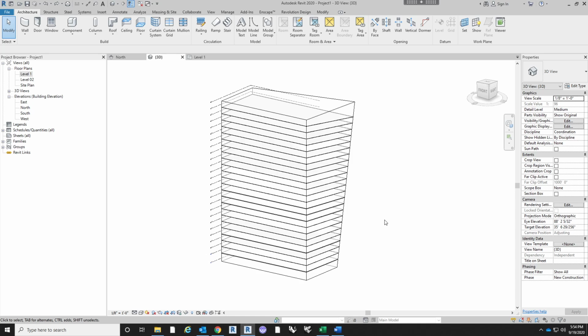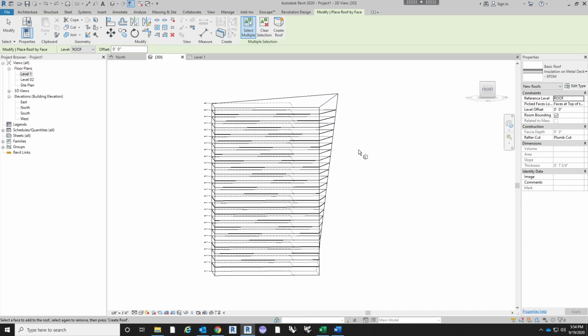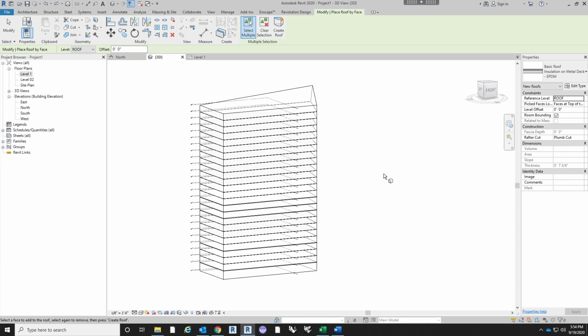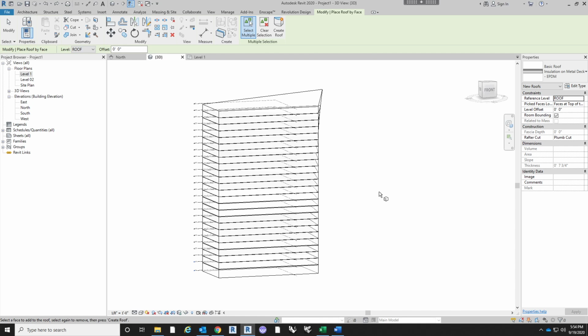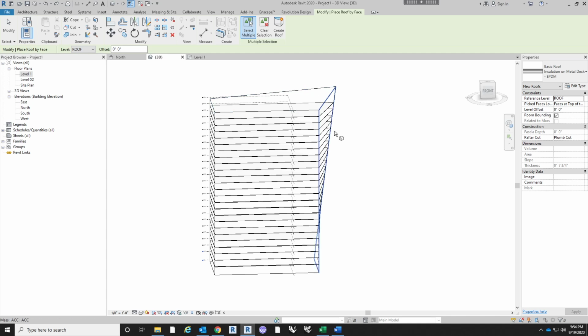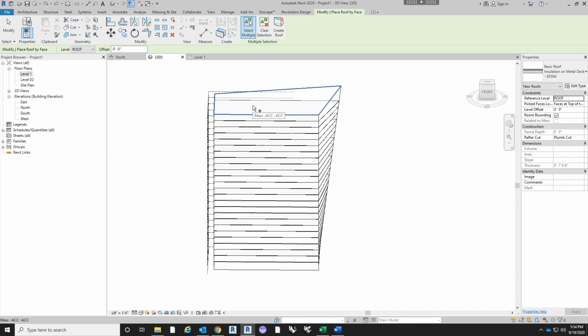Now, you can also do walls and roofs. So we'll start with roofs since that's a pretty simple one, and there's really only one thing that you can do with it. So you can do roof by face, and then you can select pretty much any face that isn't vertical, right? So if it points upward in any direction, you can apply it. So you could apply it to this face since it does turn from true vertical, but you can't select the other ones because they're purely vertical faces.